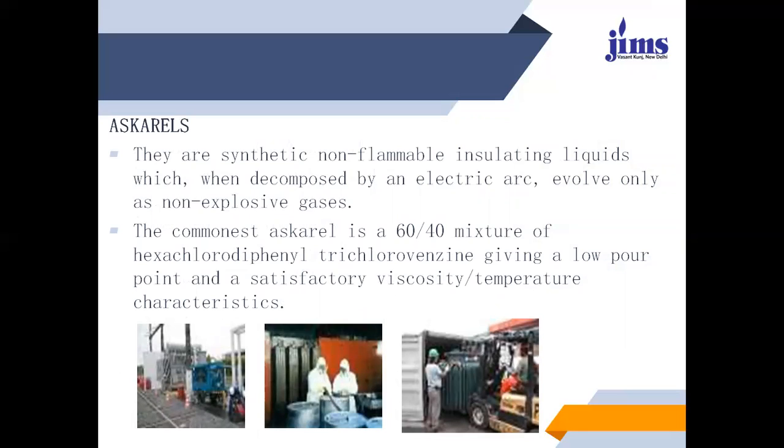Another type of material which we use is the askarels. They are synthetic non-flammable insulating liquids which, when decomposed by an electric arc, evolve only non-explosive gases.